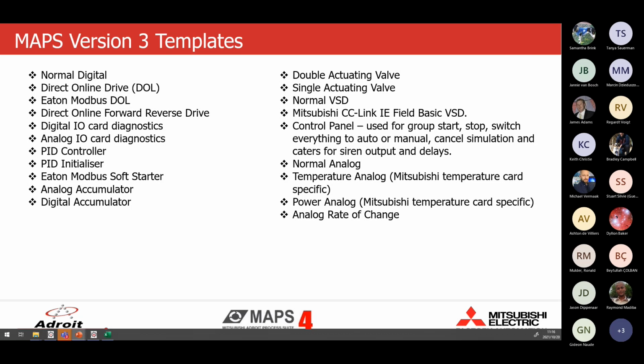The version 3 templates are more focused on the grayscale, what we now term the HMI new way of developing, where everything is gray and dull and the operator only sees color when it's really required to act or do something, which is the best practices of developing HMI. And if you ever need any more information on that front, I can point you to a book that explains it quite well.